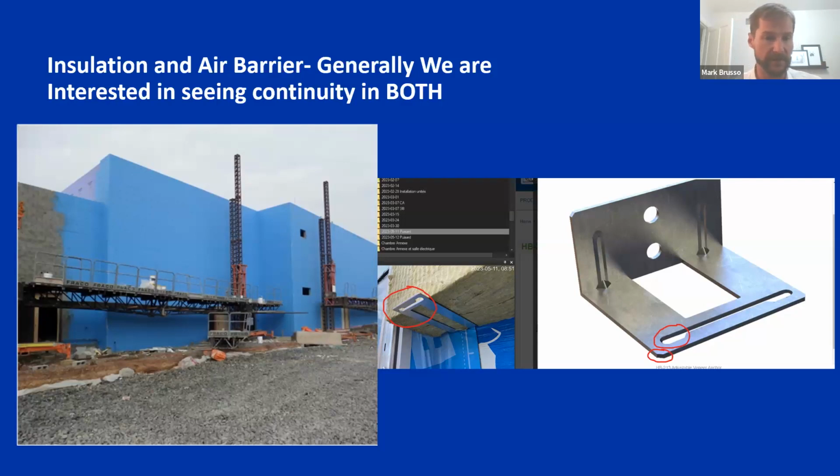And that's something that the fluid applied system does a very good job with, is that continuity of the air vapor barrier. So it's a complete plane all the way across. It would be very difficult to deal with that with a sheet applied system with that many penetrations.